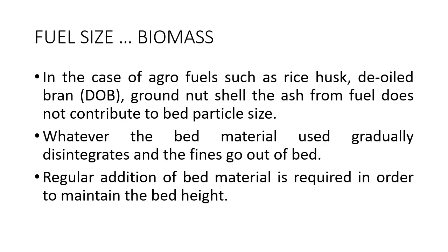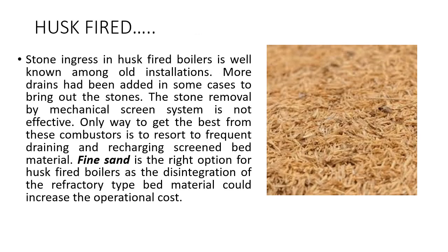In husk-fired boilers, stone ingress has to be looked into because stone ingress in husk-fired boilers is well known among old installations. More drains have been added in some cases to bring out the stones. The stone removal by mechanical screen system is not effective. Only one way to get the best from these combustors is to resort to frequent draining and recharging the screened bed material. Fine sand is the right option for the husk-fired boilers as bed material, as the disintegration of the refractory type bed material could increase the operational cost.